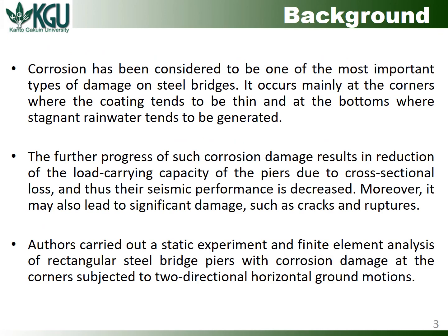First, the background is here. Corrosion has been considered to be one of the most important types of damage on steel bridges. It occurs mainly at the corners where the coating tends to be thin, and at the bottoms where stagnant rainwater tends to be generated.